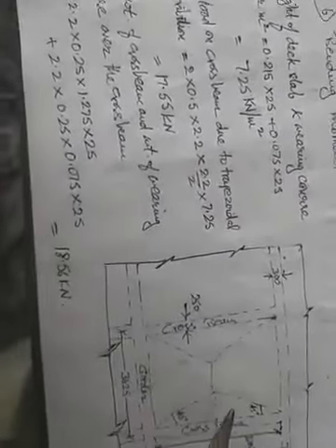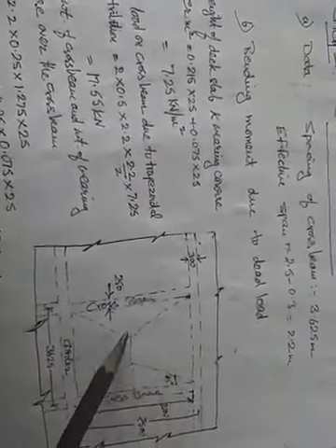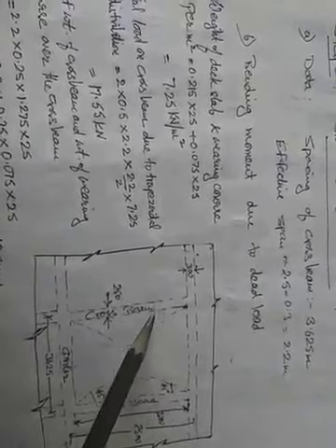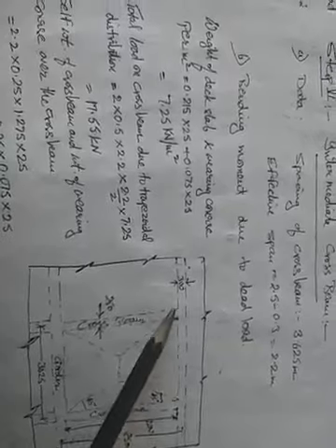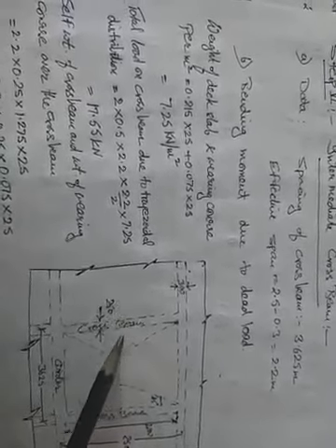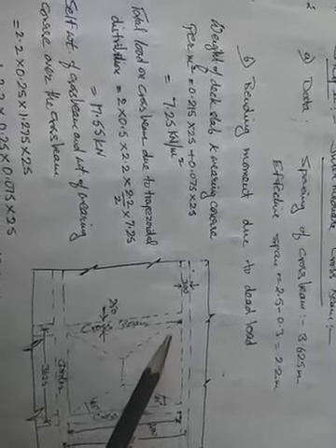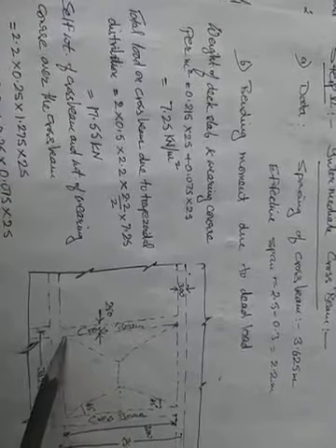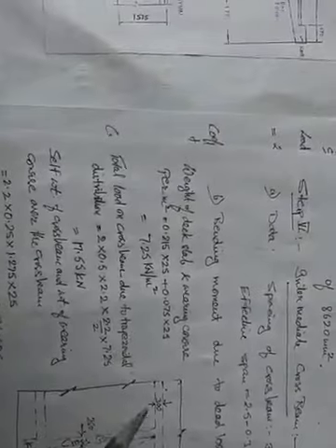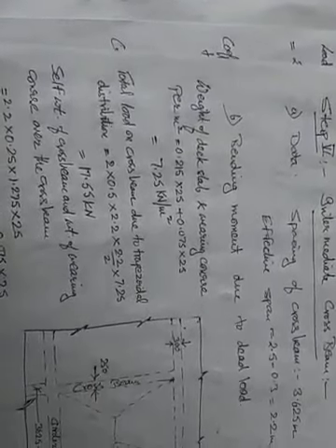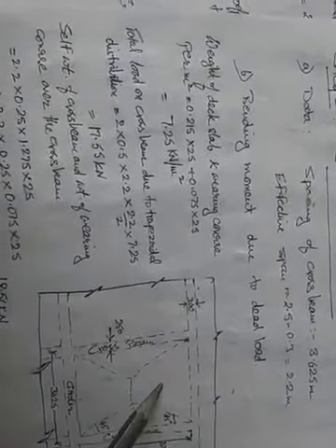So the load dispersion is trapezoidal. So you can see over here. So that means a cross beam will cater one triangular section from here and the other one from here. So this will be the load coming on the cross beam. The total load can be calculated. The load intensity can be calculated with the help of the dead load of the deck slab as well as the bearing course. So let's see.